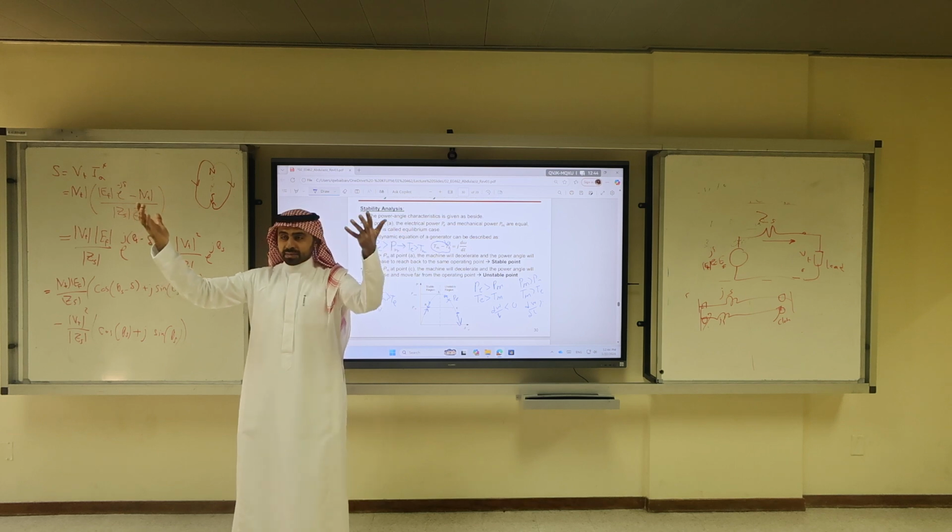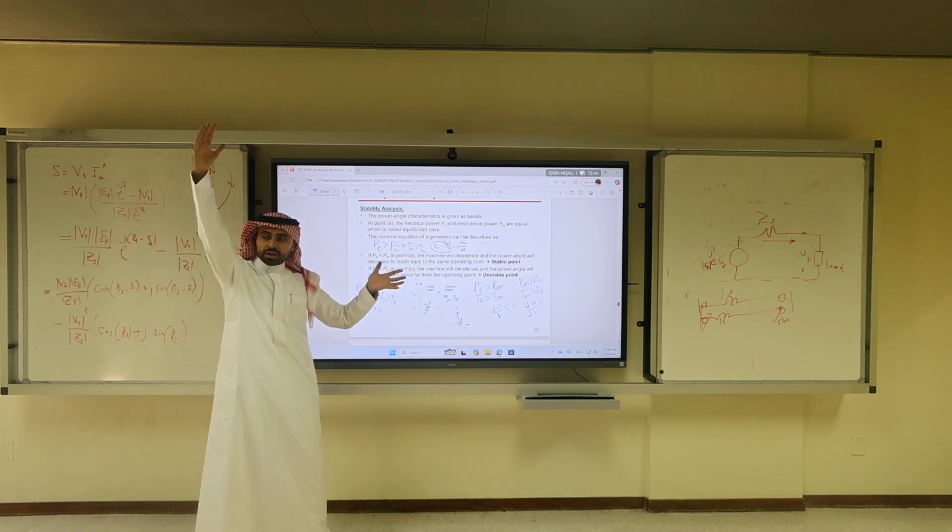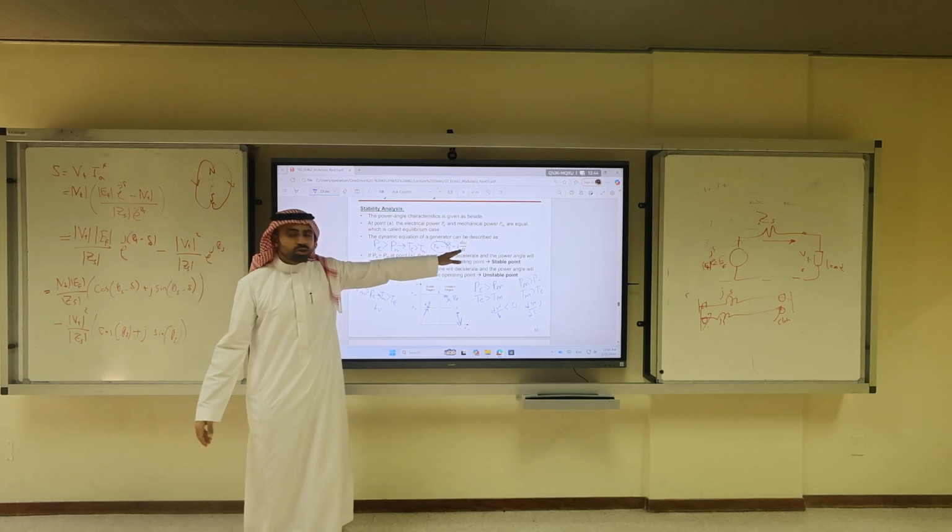By inertia times acceleration. The delta torque equals inertia times acceleration. If you have a bigger synchronous generator, the acceleration would be less.